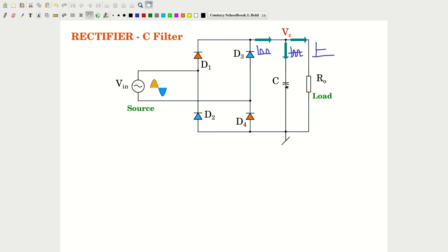You must note that in the steady state the capacitor can handle only a pure AC current. There should not be an average value, otherwise there will be charge buildup. So under steady state, the zero average part of the current, or only the AC component, flows through the capacitor. So that is the action of the filter. Now let us see the waveforms in detail.